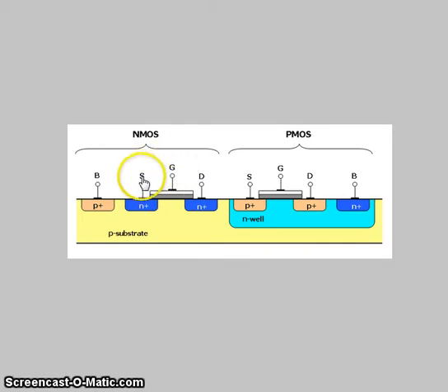In our case, the NMOS will be connected to ground, as we'll see in a minute. This drain will be connected to this source, or this drain, because it is a symmetric device. These two gates will be connected together, and this either source or drain again will be connected to high, which will also be connected here. Now, with that conversation, it's easier to illustrate this interconnectivity using a schematic.